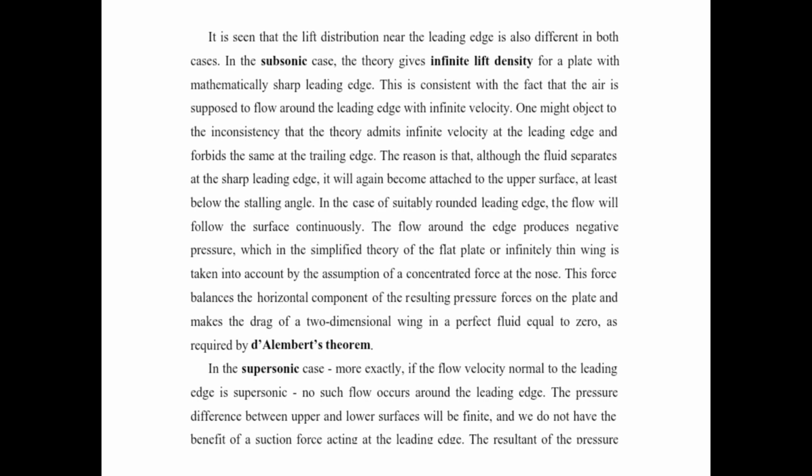One might object to the inconsistency that the theory admits infinite velocity at the leading edge and forbids the same at the trailing edge. The reason is that although the fluid separates at the sharp leading edge, it will again become attached to the upper surface, at least below the stalling angle.